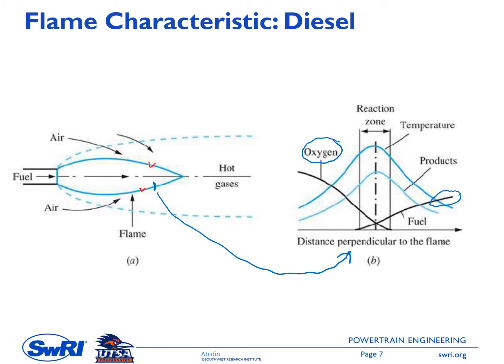So it is inside this reaction zone where the heat release occurs. You can also see here that the temperature is maximum at the center of the flame front. This one is TU, the unburned gas temperature. And here we also have a lower temperature because we still have a lot of fuel here that needs to be evaporated, so it takes energy, and therefore the temperature decreases here.